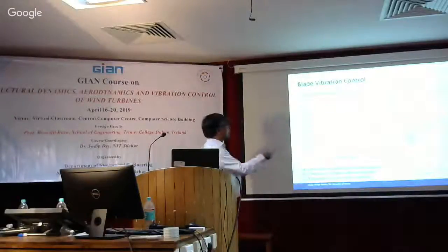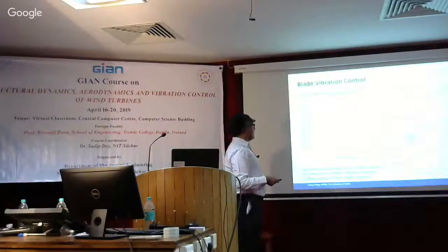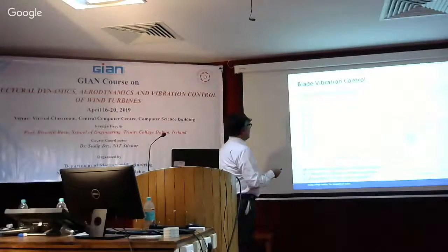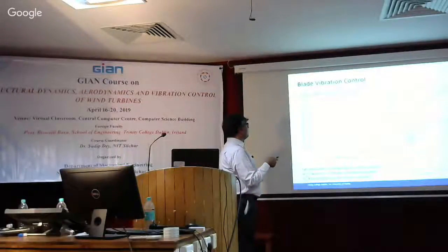So now let's go back to these curves once again and say that we can reduce the blade response in two ways. Either we can increase the pitch angle, or we can also increase the pitch actuator load. So by increasing the actuator load, we reduce the displacement response.